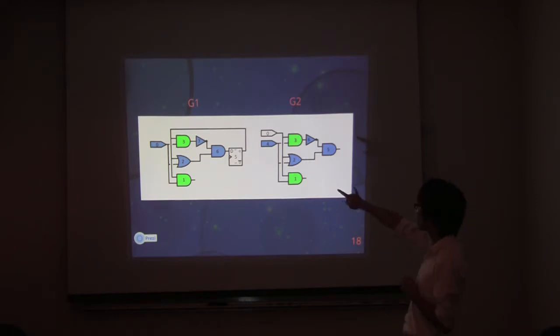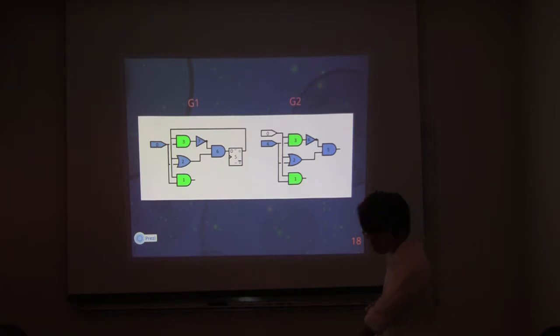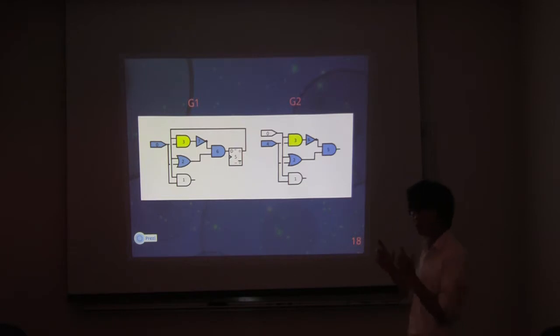So for 3 and 3, it compares the degrees going into the node. Both have a degree of 3, and for 1 and 1, both have a degree of 2, because there is no output connected to that AND gate. Because the degrees are different, it'll try and match 3 and 3 first. If the degrees are the same, it'll check the next component in the path. If those are still the same, then it'll arbitrarily choose one path.